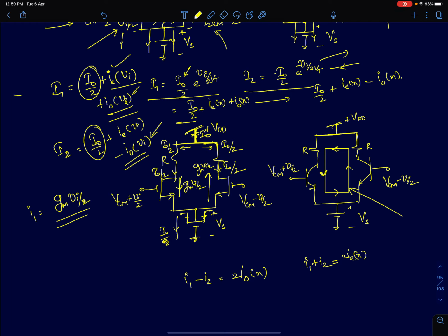So if you look at the small signal current, the first harmonic current, none of it is flowing into the ground. It will just loop in this way. And in the same way, none of the odd harmonic current is going to flow through the supply as well, because any current that's entering here, since its polarity is the same here, it has to leave. So no current flows through the supply. As far as the supply is concerned, there will be no odd harmonic currents drawn from the supply. The odd harmonic currents will form a loop this way.